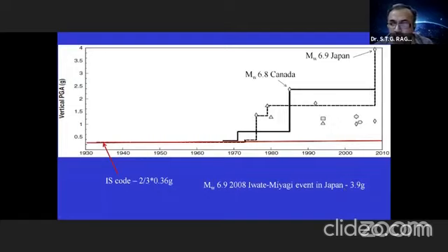Now, when you talk about the future, say the next 50 years or the next 100 years, will the maximum vertical PGA be the same as 3.9 or will it be more? It's very difficult to answer actually. The data is also showing an increasing trend. So how much maximum PGA can be observed due to an earthquake? It's a very, very difficult question. People have tried to model it by statistical approaches, but all have failed actually. They were unable to predict the maximum PGA at all.